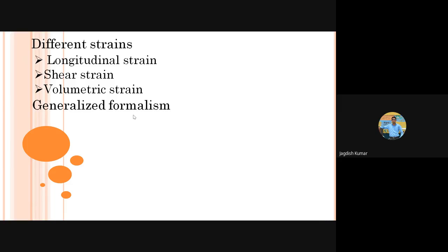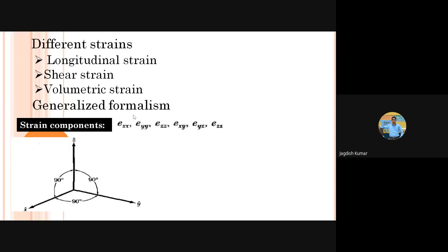So let us now try to discuss that generalized formalism and try to understand those stress strains. And then we will be applying this to a simple case of cubic crystals. We will keep our life simple. Here we will only be discussing the generalized formalism, or a method. Then we will apply that method in the simplest case. If you want to make it more generalized, then you may have to do a little more complex analysis. But okay, we will be discussing those generalized aspects.